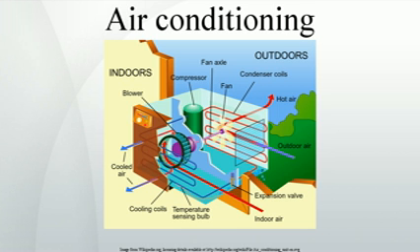Evaporative coolers. In very dry climates, evaporative coolers, sometimes referred to as swamp coolers or desert coolers, are popular for improving coolness during hot weather. An evaporative cooler is a device that draws outside air through a wet pad, such as a large sponge soaked with water. The sensible heat of the incoming air, as measured by a dry bulb thermometer, is reduced. The total heat, sensible heat plus latent heat, of the entering air is unchanged.